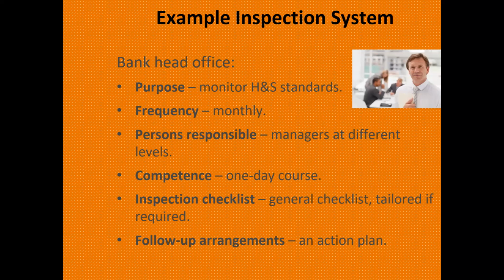There is no hot work, there is no lifting, no confined space, no excavations, no access or egress issues. There are fire hazards, but not much, like workplace conditions. There are no chemical, no flammable, no combustible materials being stored. So the requirement is very easy and light in terms of hazards.